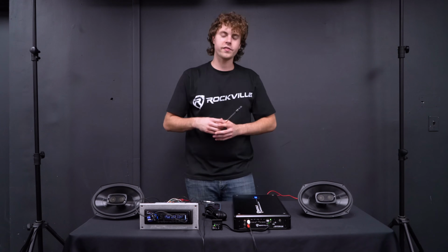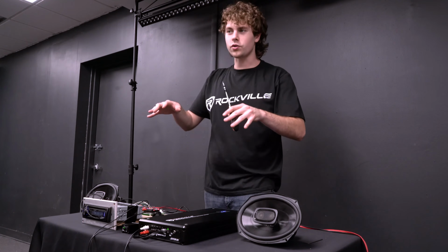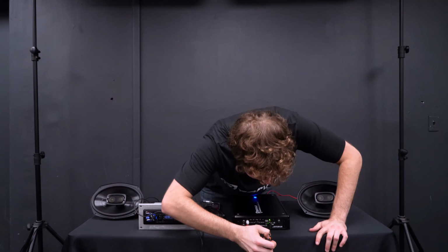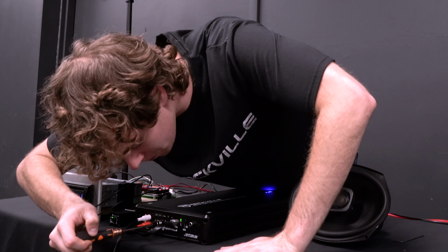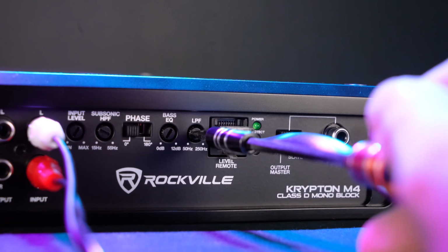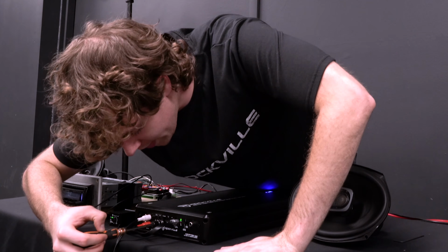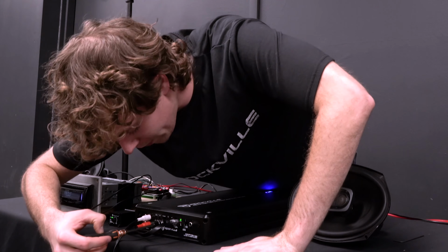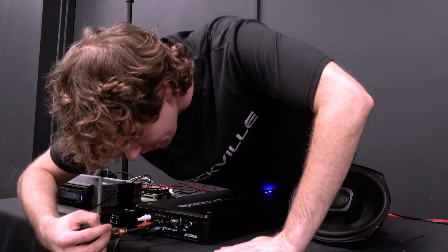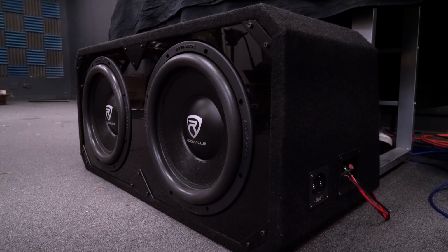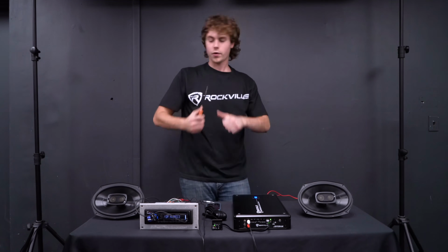So right now we have some music playing through the sub. There's vocals in this track that you'll hear through the sub because it's set at the 250 Hertz. So we'll start to bring that low pass filter down. So now we're hearing less of the vocals, more of those bass tones from the bass and the kick. And now we're just hearing bass and kick, which is right where we want it to be.